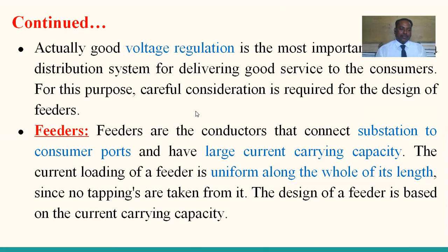Feeders are located from the distribution substation onwards up to the distribution transformer. The distribution transformer is located in load centers, and the distribution substation is located outside the load center. Therefore, a connection is required from the substation to where the transformer is located, and that is nothing but the feeder.